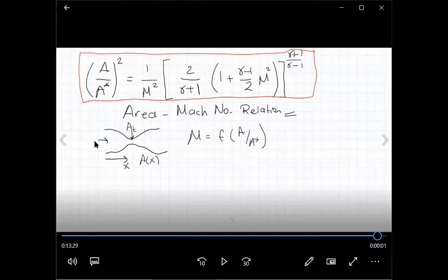And in most of the fighter aircraft engines, the engines are equipped with what we call only a converging nozzle. So there's no diverging part. There's only the left-hand side part. It comes in from a large area, and it basically gets into a minimum area location, and that's it. That only has the converging part, and the amount of minimum area is controlled.